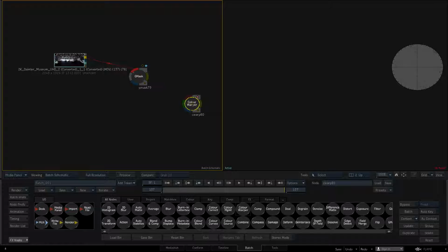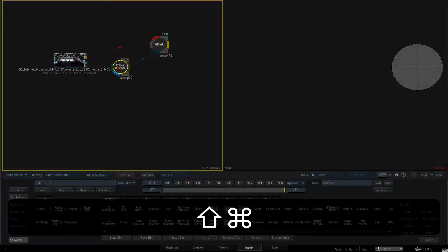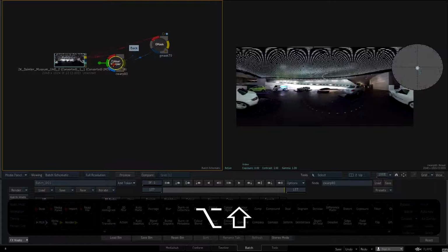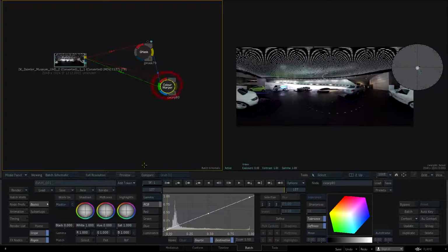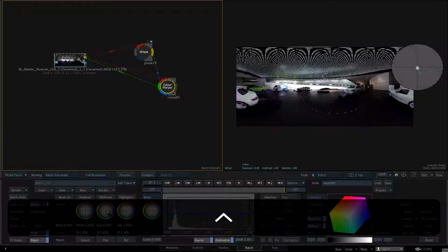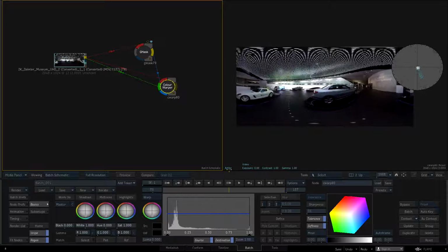I'll parent its front and back inputs off of the source clip and parent its matte input off of my imported Gmask. Now the Gmask is used to hold out the grade I apply in the color warper. I'll push the brightness, contrast and gamma of the car in the color warper in order to make it stand out better.